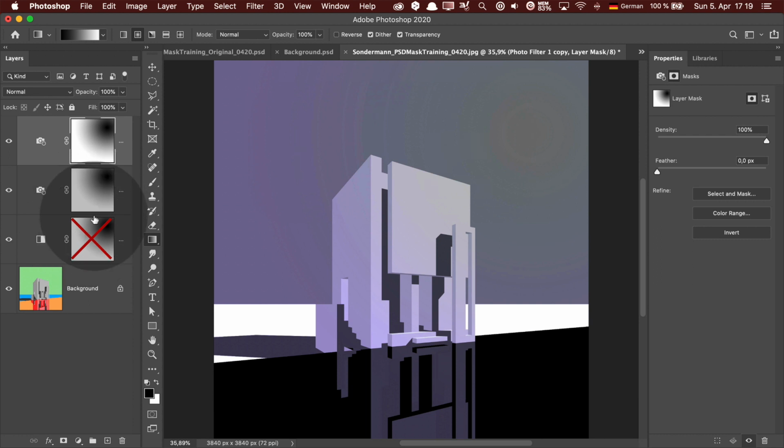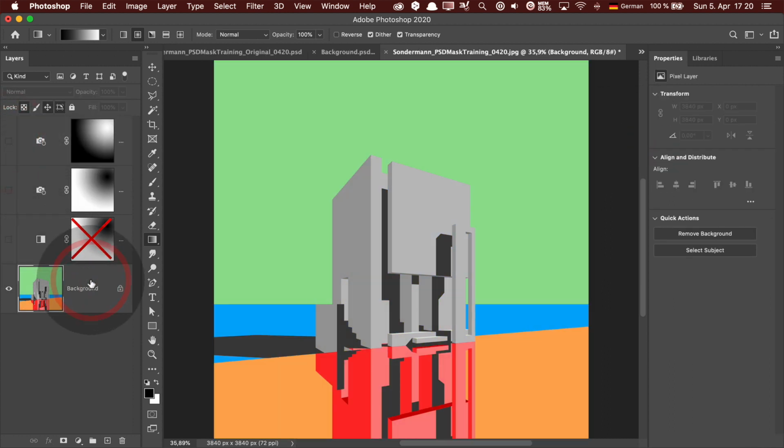And now you might want to do something about these masks. For another feature of masks, you see in the properties panel, you can invert them. And now you have this blue filter showing exactly in the part where the other one is hidden. Looking at the properties panel, you see there are some more options. You can also diminish the mask effect by just reducing the density. And as you can see in the miniature, it's turning white when scaling it down to 0%. Let's hide all those new layers and take a look at our original image.